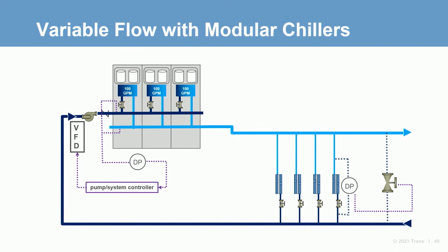As the automatic isolation valves modulate open and close, the pumps track up and down, maintaining design flow to the number of operating modules. As an alternate control strategy, the pumps could also be controlled to maintain a system pressure. Either control method should be fast-acting and not go through a BAS that could slow down the control response. In either system, it is recommended to use high-quality components with high accuracy capabilities. The system side would operate in the same fashion as the previous example.